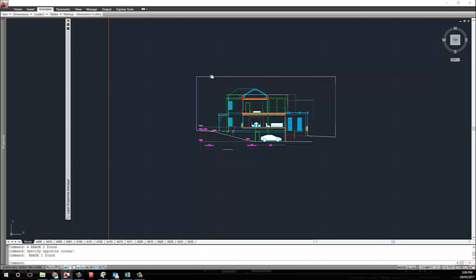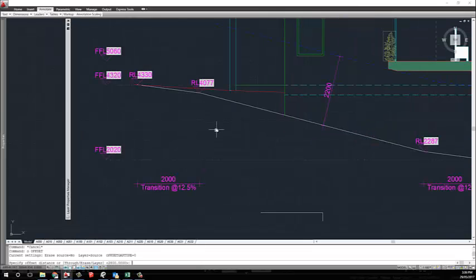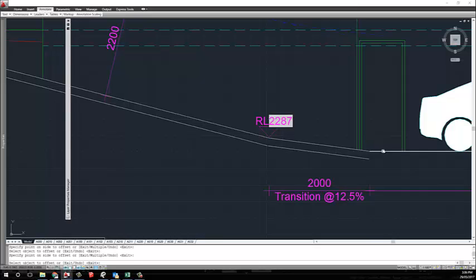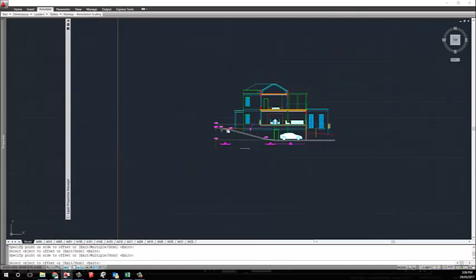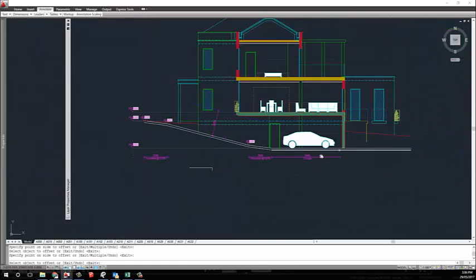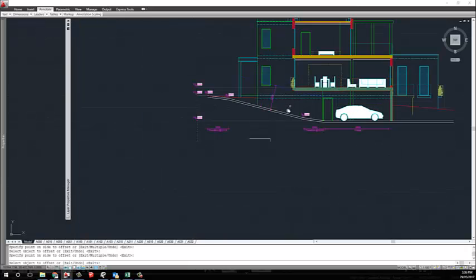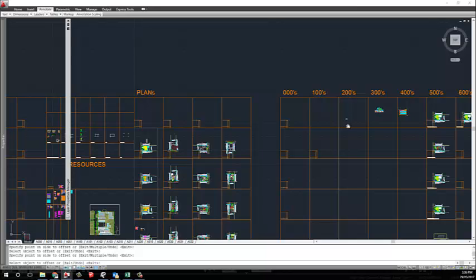We also don't need this, which is the neighbor, the other building. So now we need to add a bit of detail. We give the thickness of the slab, maybe 150, and instead of this ugly green hatch, which is mandatory in Woollahra Council because it represents concrete, we give a concrete hatch, and that's it. So Woollahra Council needs to know this, and probably we need to leave a space in the page for a front view, but we don't need to worry about that today.